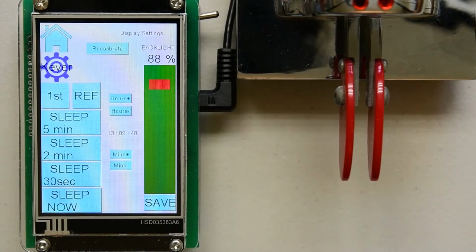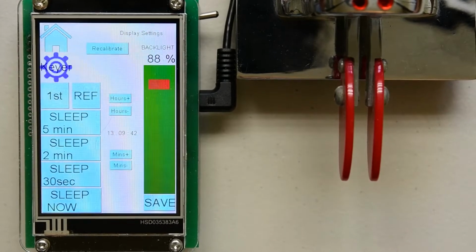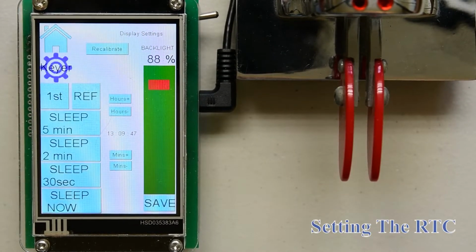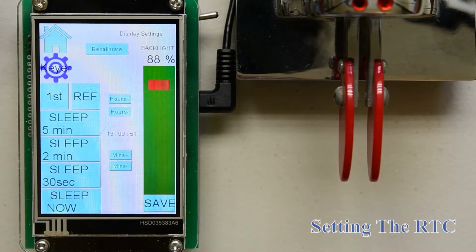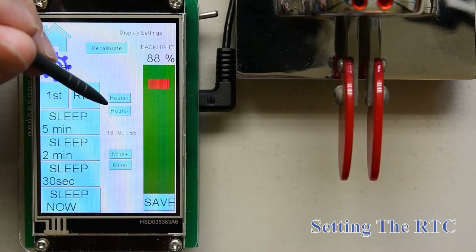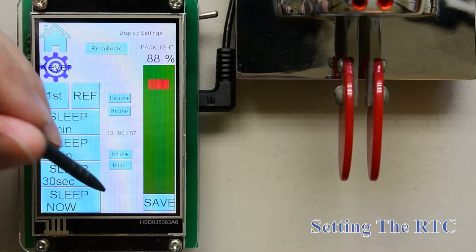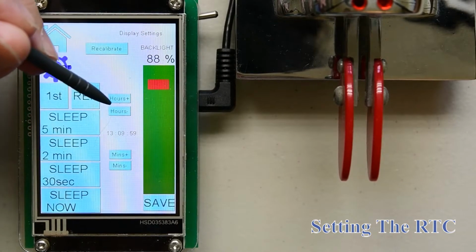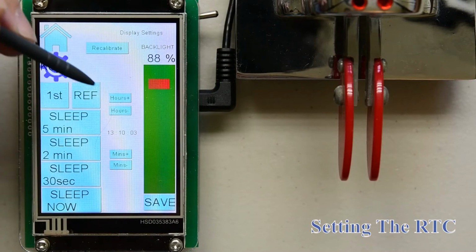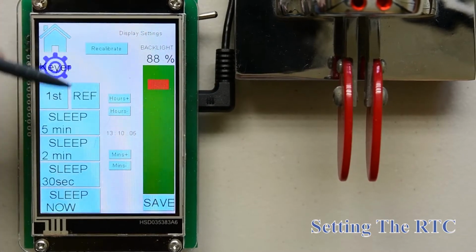The enhanced Nextion display used in this project includes a real-time clock. The real-time clock gets its power from that battery holder in the back of the display. To change the time of the real-time clock, you use the hours plus and minus and minutes plus and minus buttons on this page. The hours plus and minus do what you would expect, increase and decrease the hours.